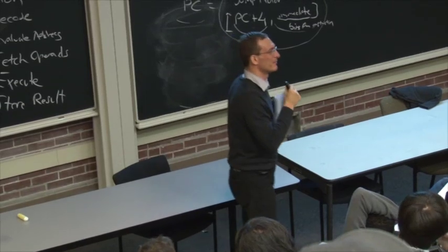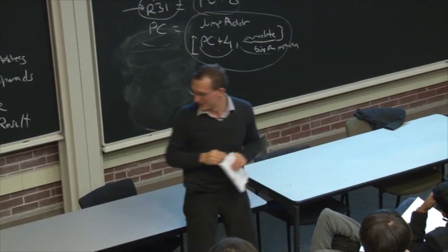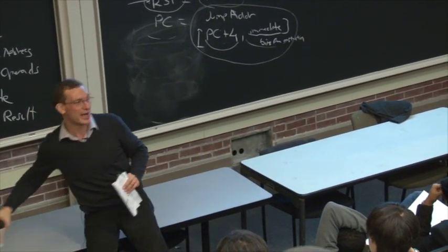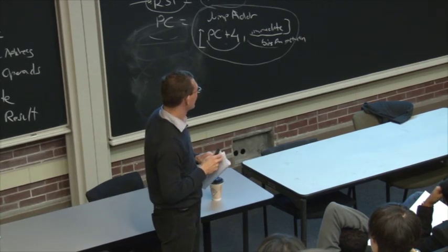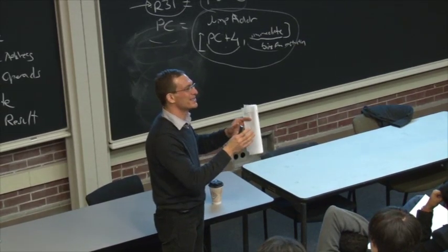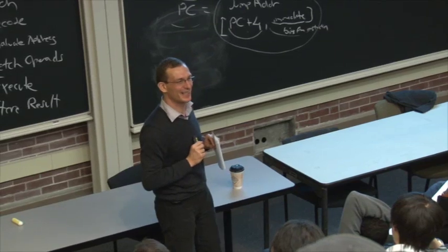Yes. So for the single cycle then, everything with the control signals is combinational? There's no FSM or anything? Absolutely, yes. That's the beauty as well as the Achilles heel of the single cycle microarchitecture, right?